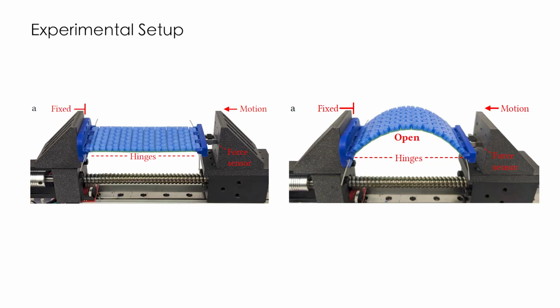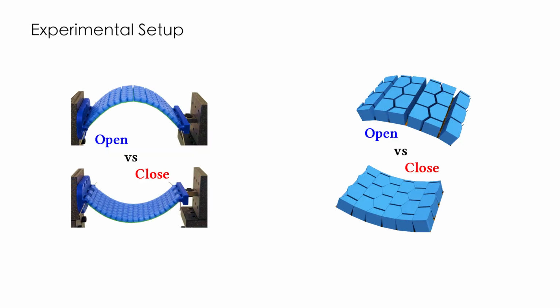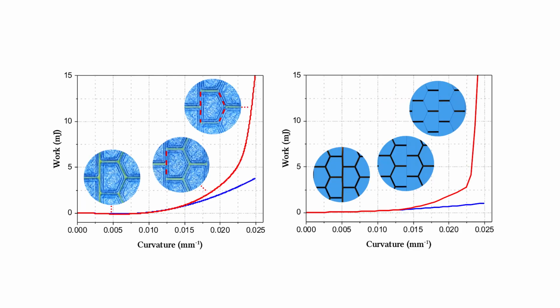As another characteristic effect of scaled sheet materials, we furthermore evaluated the asymmetric stiffness of scaled sheet materials for positive and negative curvatures. For better clarity, we refer to curvatures as opening or closing to indicate an increase or decrease of the gaps between scales, respectively. In this example, the stiffness for opening curvatures is very low and stays roughly constant. The behavior is initially similar for closing curvatures, but once scales start to make contact, a significant stiffening is observed.